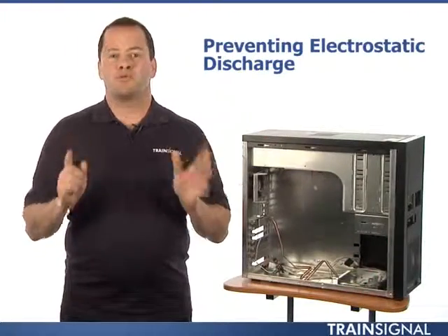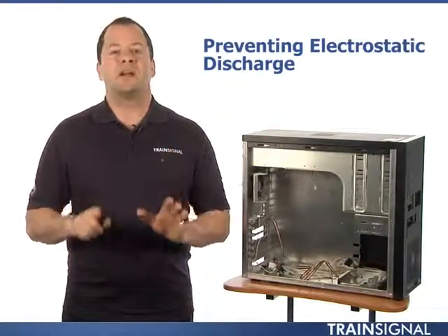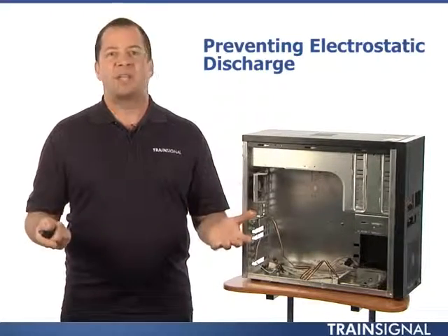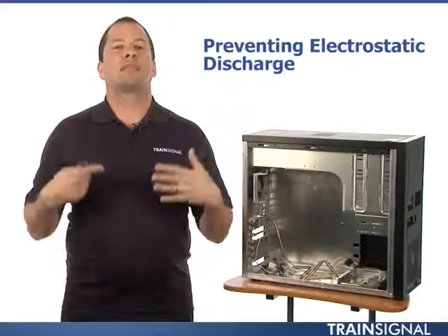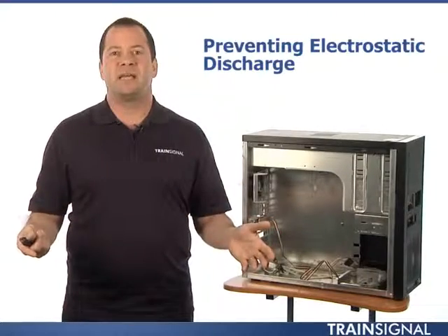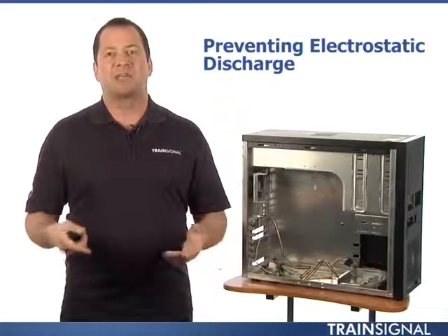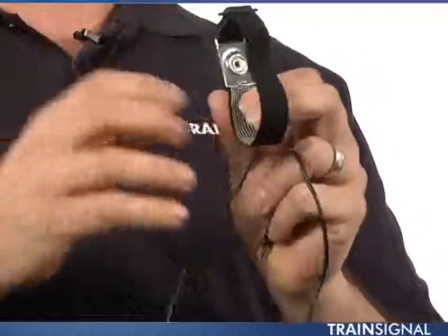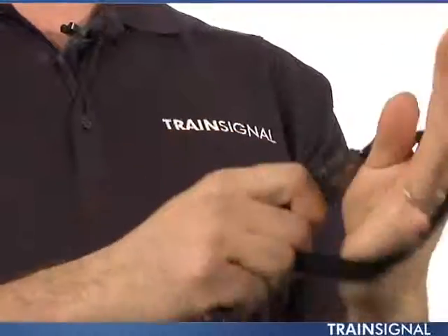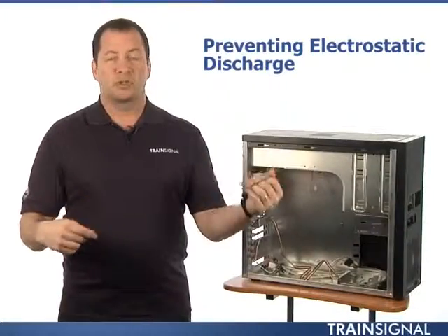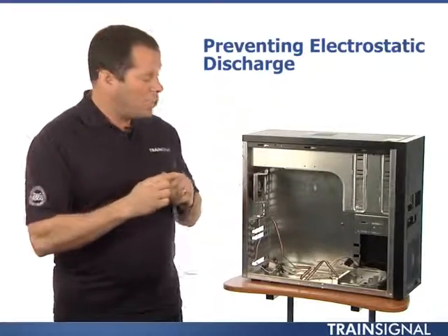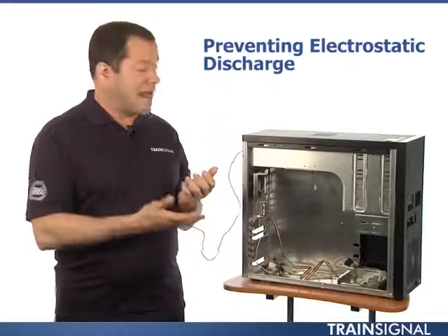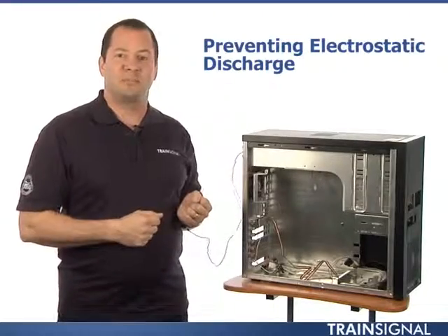In just a moment, we're going to proceed with the installation of the motherboard, but it's very important that we take note of electrical safety first. One of the things that can happen in touching computer components is what's called electrostatic discharge, or ESD. The way to prevent that and damage to the components is to use a device like this called an electrostatic wrist guard. You can see it just very simply slips on like this. There's a little alligator clip at the end, and it's important to be able to place this on some metal portion of the chassis. And now we're grounded and ready to proceed.